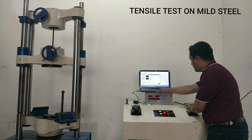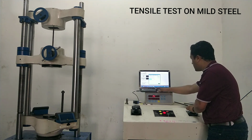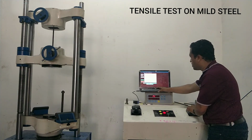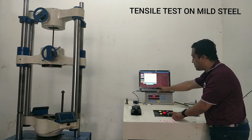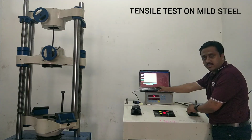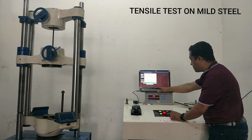You have to input the diameter, which is 12 mm, the gauge length, which is 450 mm, and start with the experimental setup. This is the screen where we will see load versus displacement. Now we'll start the load on this control panel, and at the same time start on this graph, and start opening this load regulation valve, meaning start applying the load on this bar. We will start.